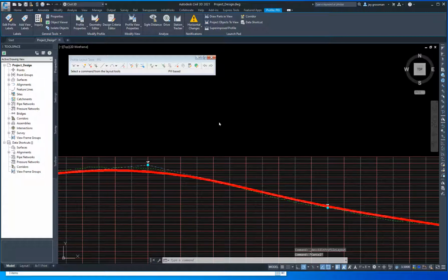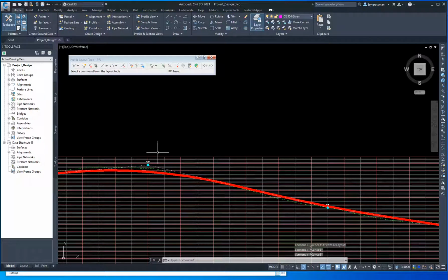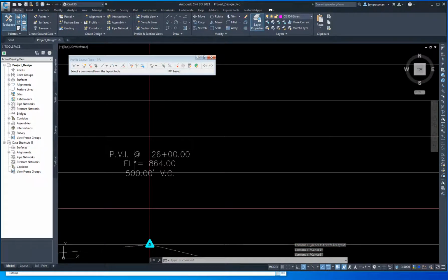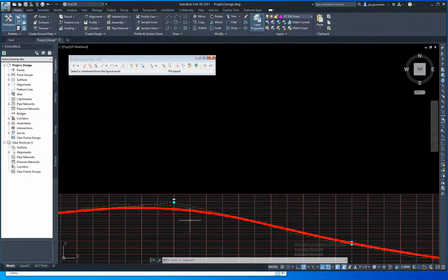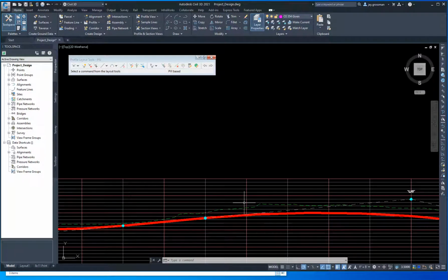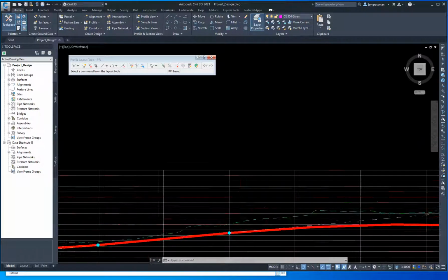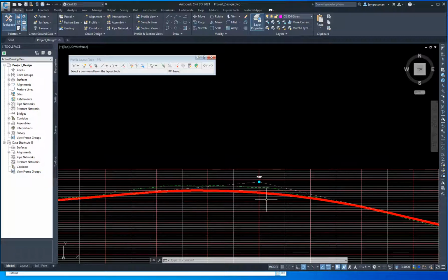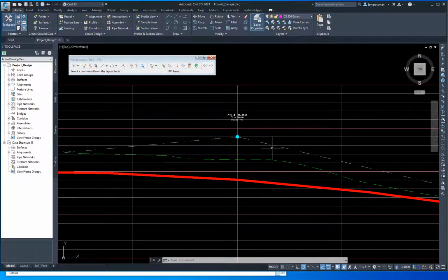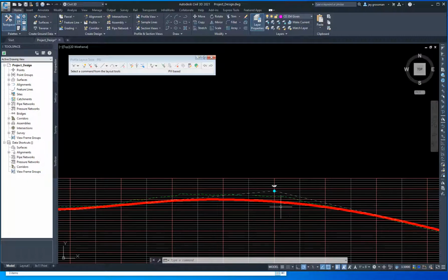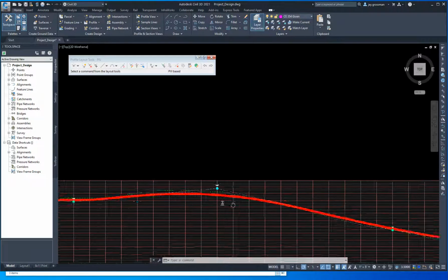Through that, hit escape when you're done. And then whatever changes you made, it's going to update your labels now. If you move stuff around, it's going to update all those labels. And then you're going to ask yourself, each one of these lines is 1 foot. And you can say, do I want to be 3 feet below the existing ground here? Maybe I do, maybe I don't. Maybe that's a lot. If you're over 5 feet different, you better have a good reason for it.